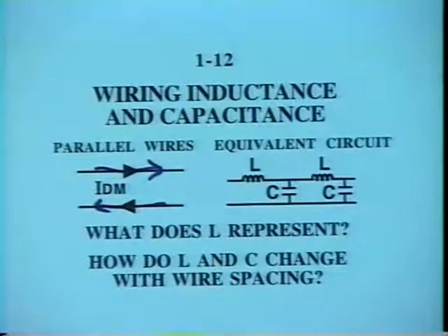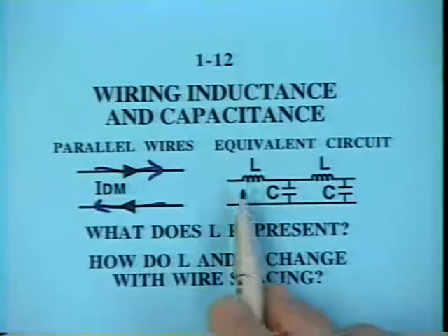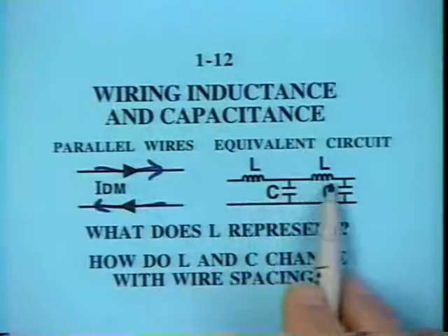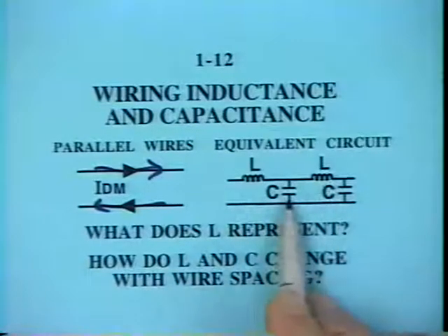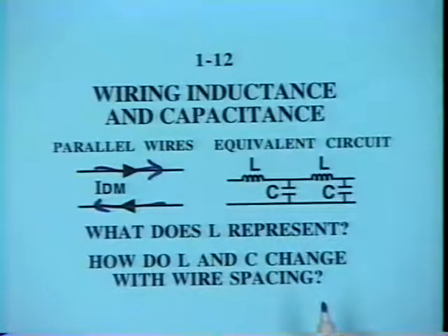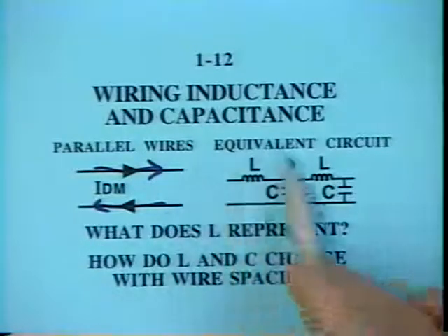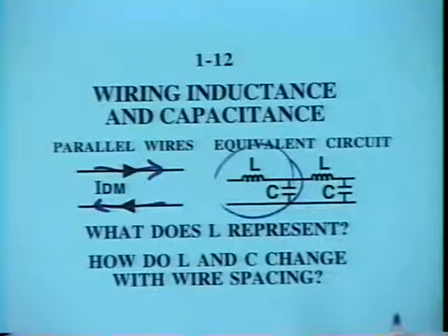We said the model for these two conductors is, in this case, distributed series inductance and a distributed shunt capacitance. There's resistance here also, but I'm assuming that compared to the other elements this is negligible or not that important to us. So the question is, how do we think about these inductors and capacitors we've shown here? And do they have any relationship to one another?